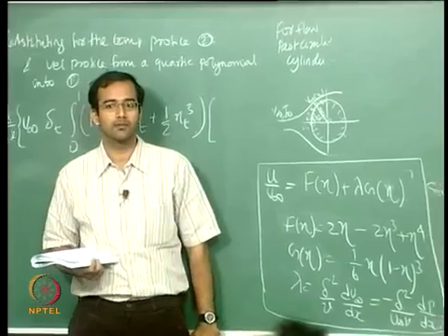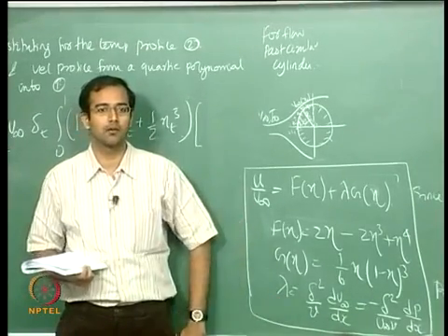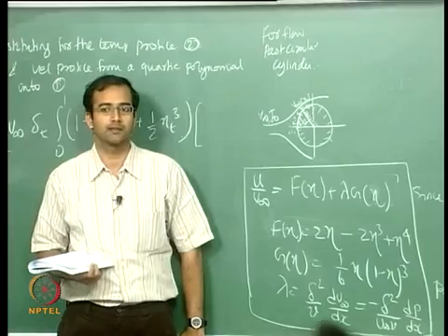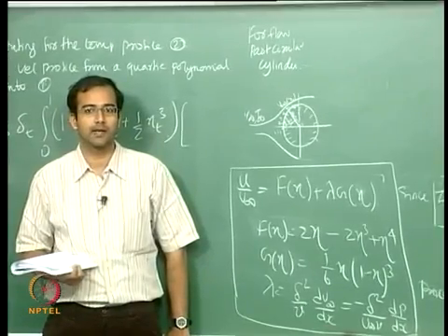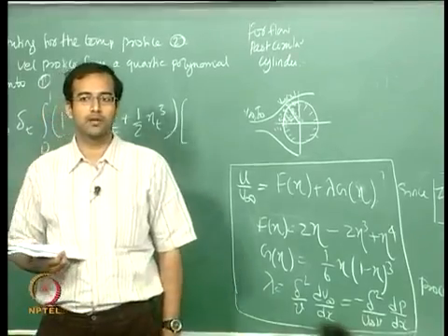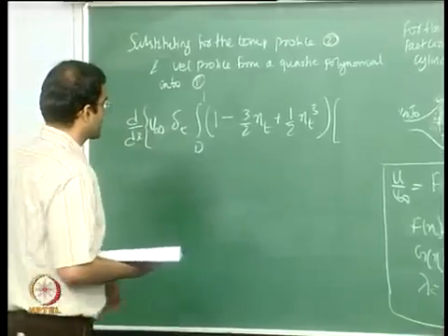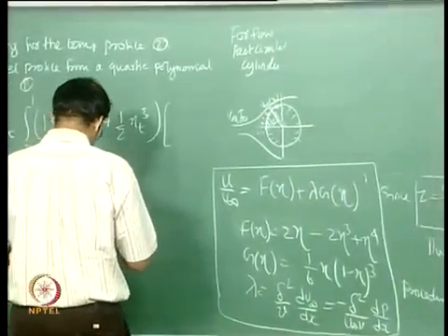Okay, so this is one measure of how adverse the pressure gradient you maintained is, and the criterion for separation is given by lambda. So lambda equal to -12 indicates the point of separation. Okay, now from this we can substitute for the velocity profile.